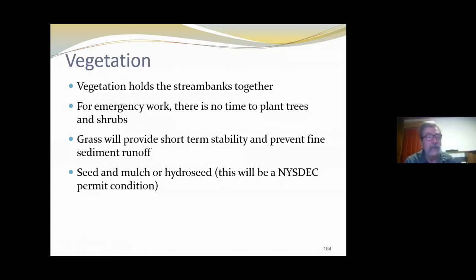After we've done construction, that material has all been loosened up, so we have fines segregated from some of the larger stuff. Until that vegetation starts to come in, we have that threat of erosion cutting some of that material away and washing it away. So we want to get vegetation on there just as quick as we can.